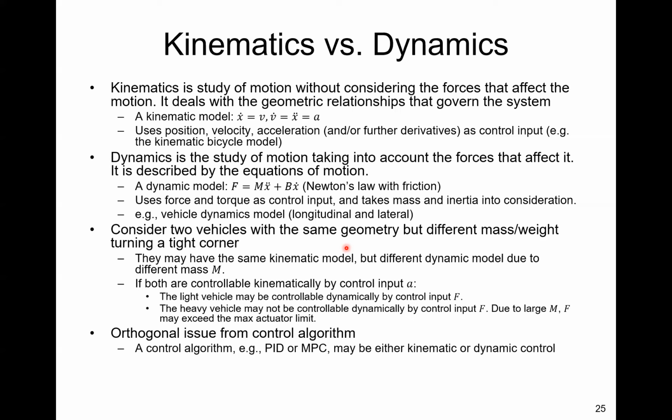So that's the difference between kinematics and dynamics. This is an orthogonal issue from the control algorithm. So PID or MPC may be based on either kinematic equations or dynamic equations. The algorithms can be applied to both situations.